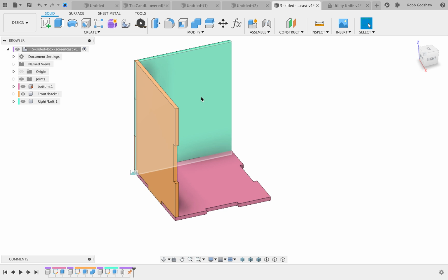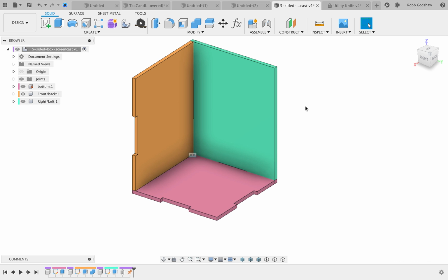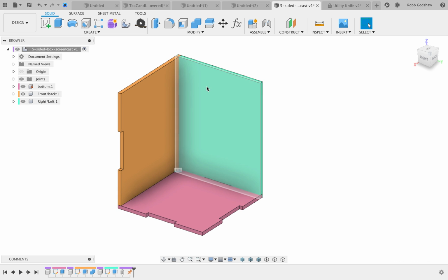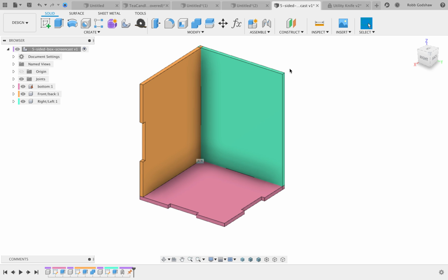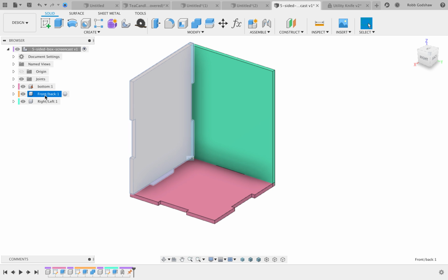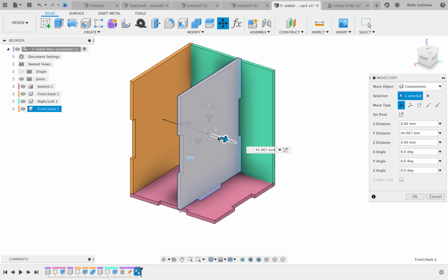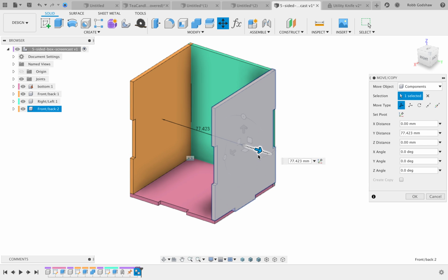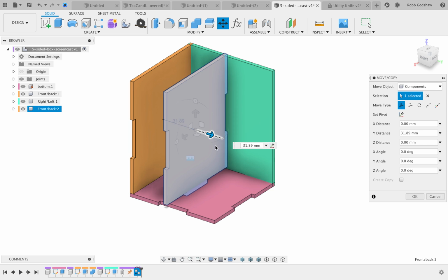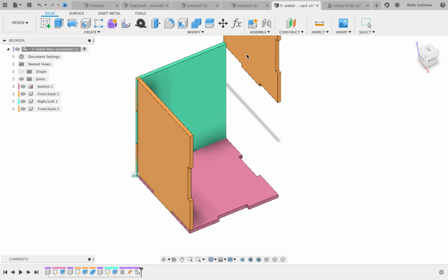Next thing I want to do is I don't want to mess with the green one yet because we haven't yet made it correct, and I'm kind of nervous about making joints between geometry when I'm about to change the geometry. So the first thing I want to do is I want to make a copy of this, and for this one I'm going to use it as an opportunity to just use copy and then paste, and you see it makes another instance right here, the number 1 and the number 2 of the same component. And I could move this, and I could be precise with the movement, and I think I could probably even use parameters for the movement, and maybe it would work, but it's a better practice to actually use regular joints in this case. So this is free to move anywhere.